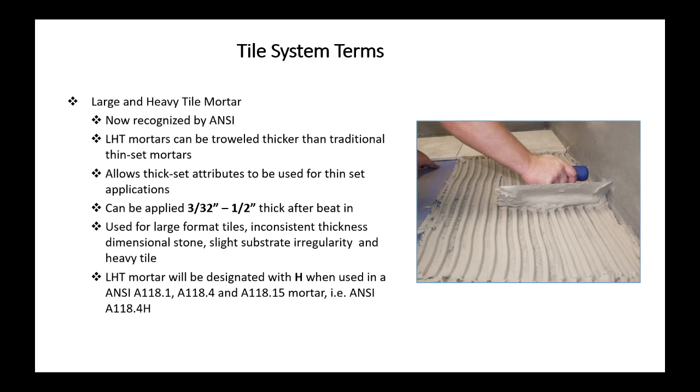It's typically used for large format tiles, tiles with one edge greater than 15 inches. When a tile or stone is inconsistent in thickness and you're trying to even that out, maybe a small slight substrate irregularity or a very heavy tile.